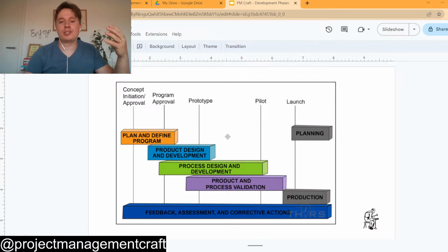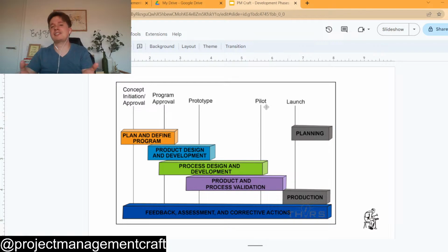So you are going to reach a maturity if you pass, of course, everything in your design validation, you follow your process development, and at some point you reach maturity in your process, and you can have what in this example is called pilot. But what's that? It's basically another type of prototype with a higher maturity. What I mean by a higher maturity is something that was already produced in a manufacturing line, in a serial production mode. That's something that's 100% representative of what you would have in production, of course only in lower quantities.